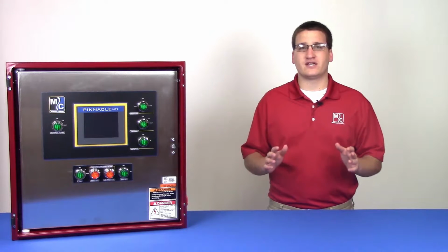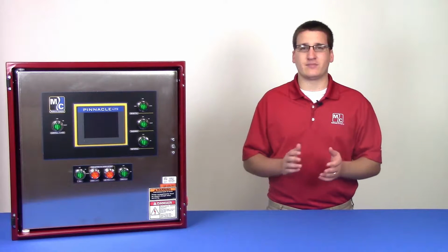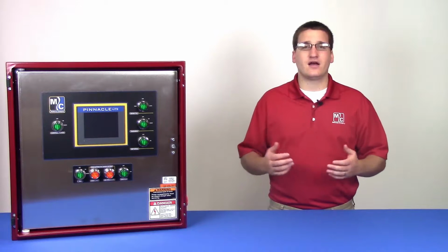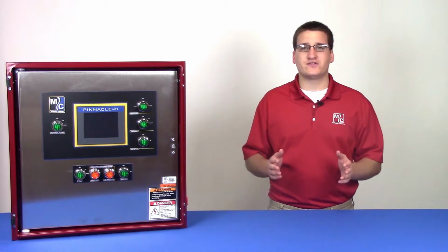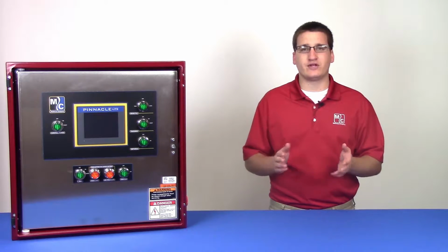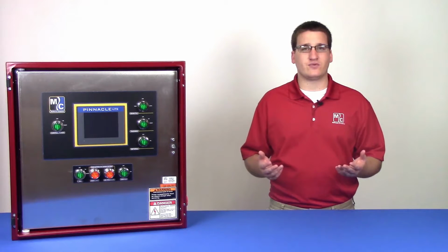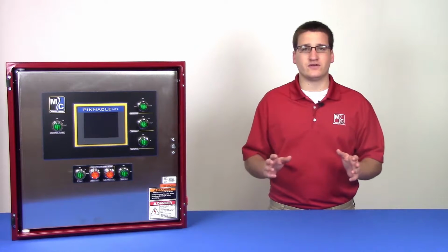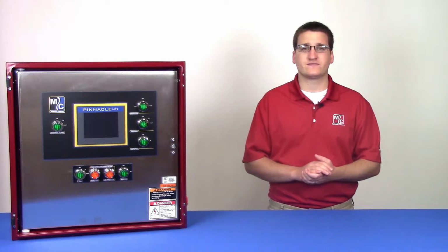Alarm set points and operational set points provide the user with a framework with which they can control and constrain the operation of the dryer. Operational set points are used to give the dryer targets to operate within, while alarm set points have the ability to alert the user under a warning condition.